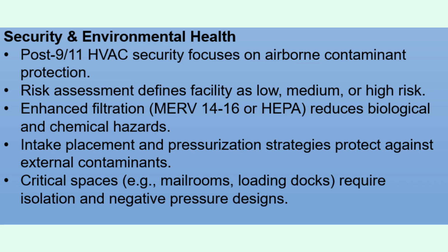HVAC systems play a major role in building security and health protection. Designers must consider threats like chemical, biological, or radiological contaminants. High-risk buildings, such as airports, hospitals, or government facilities, require advanced filtration like MERV 14 to HEPA filters and isolated ventilation systems for sensitive zones. Air intakes must be placed away from potential contamination sources, such as loading docks or streets. In critical areas, negative pressurization can prevent hazardous air from spreading to occupied spaces.